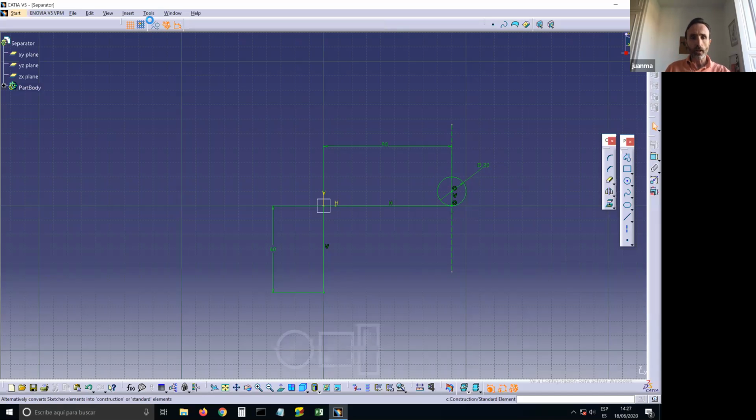And then I'm going to draw another auxiliary line so that I can cut the circle as I want to cut it. I set the angle between these two lines to be, for instance, 30 degrees. And then I'm going to trim by means of this eraser. Perhaps 60 degrees is okay. I'm going to erase the part of the circle I don't need.